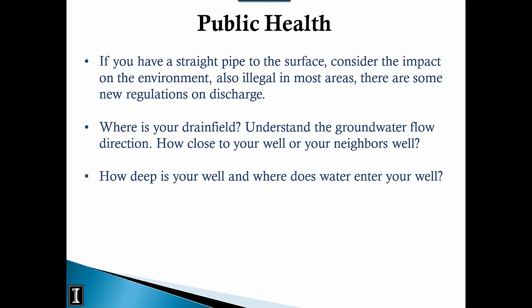And also, there are cases where your well is really deep, and knowing where your water enters your well goes to the fact of whether you have a bedrock well or a sand and gravel well. Typically, a sand and gravel well has a screen at a given interval. So for instance, a 200-foot sand and gravel well likely has a screen in the bottom 5 feet or so. So that means the water can only get in the well from 195 feet to 200 feet of that well.